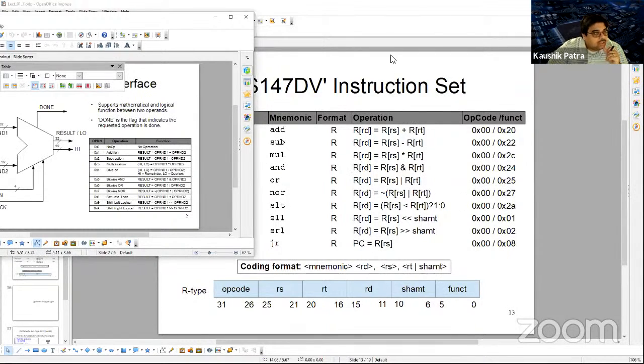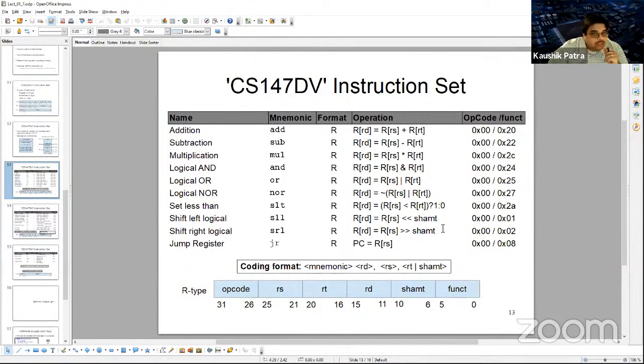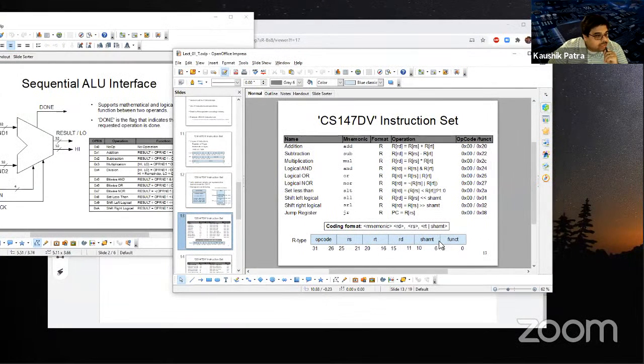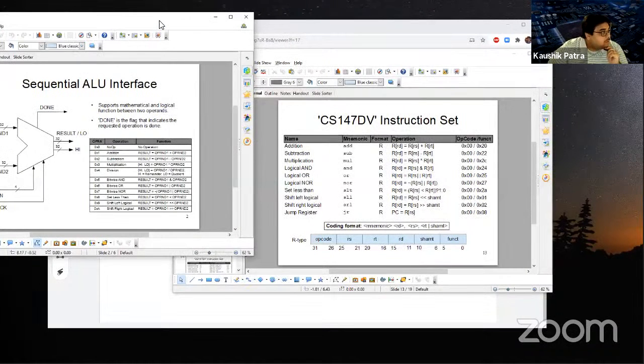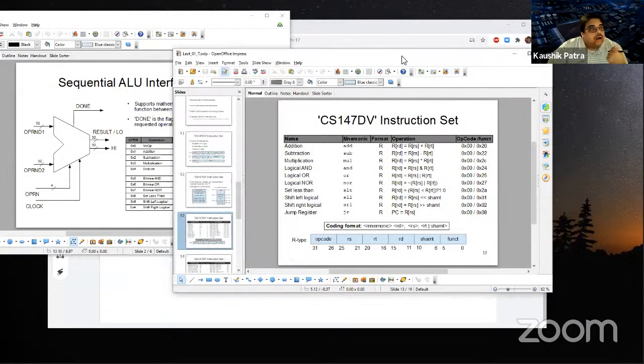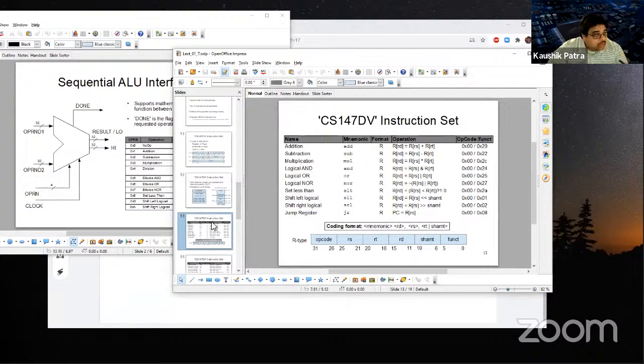It is nothing coincidental with this, isn't it? They're not the same. So this is for machine code construction and how the processor understands what instruction is being executed. And then this operation code is for the ALU, instructed by the controller, to say what arithmetic or logic operation it needs to perform and give the result on. Make sense?